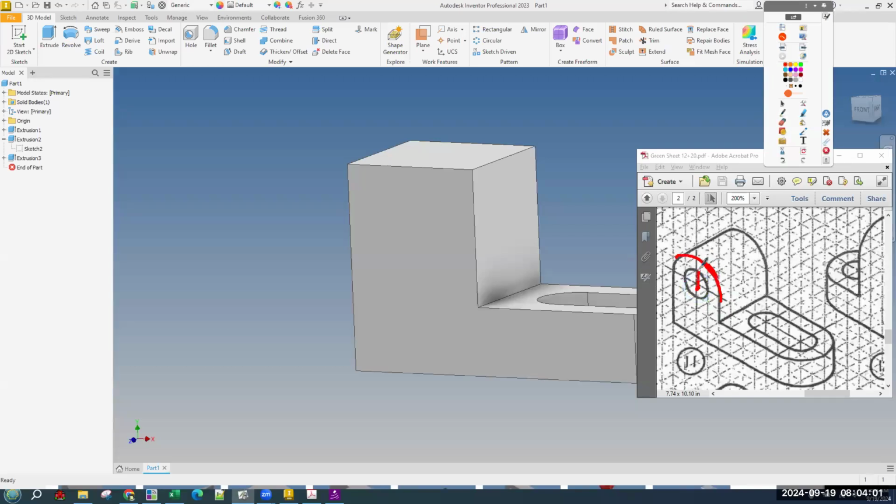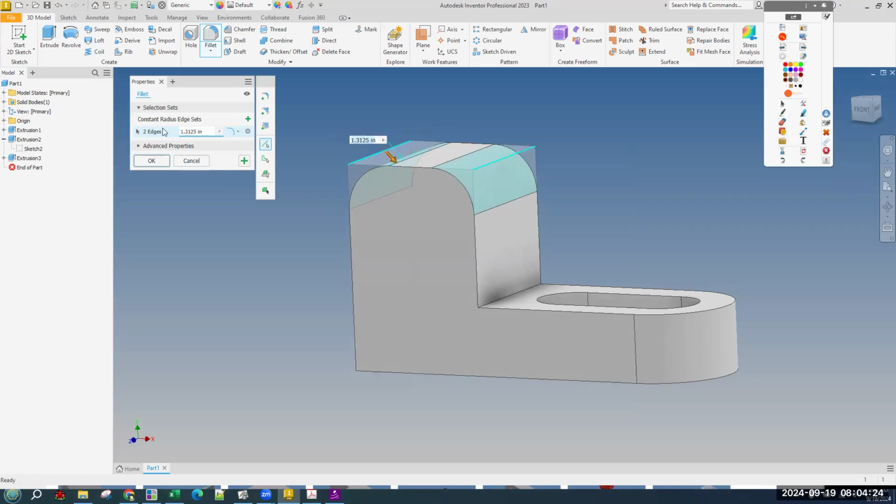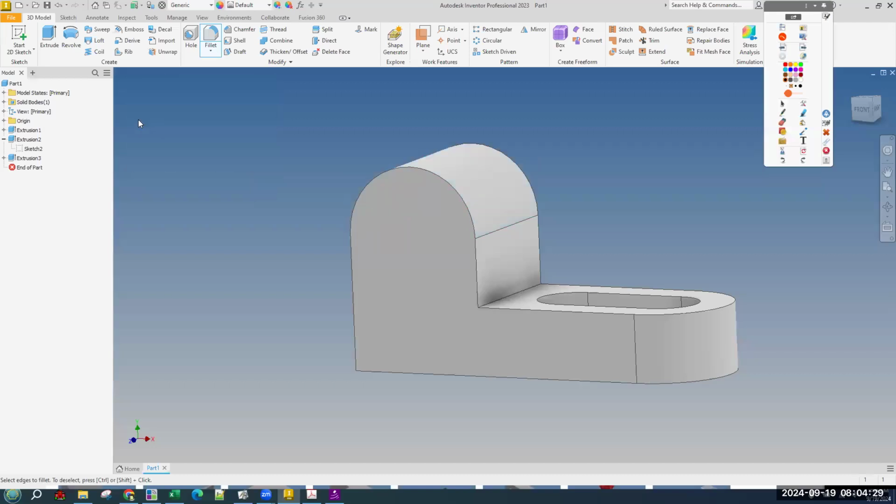And we know, again, from these like little construction lines, these extension lines, we can see that this point right here is the center, and it's a distance of 2 in every direction, which is the radius. So we're going to get the fillet tool and click on this edge and click on this edge. And the dimension we want is 2 because it's 4 all the way across. If we make it 2, it's actually like a double fillet that smooths over.